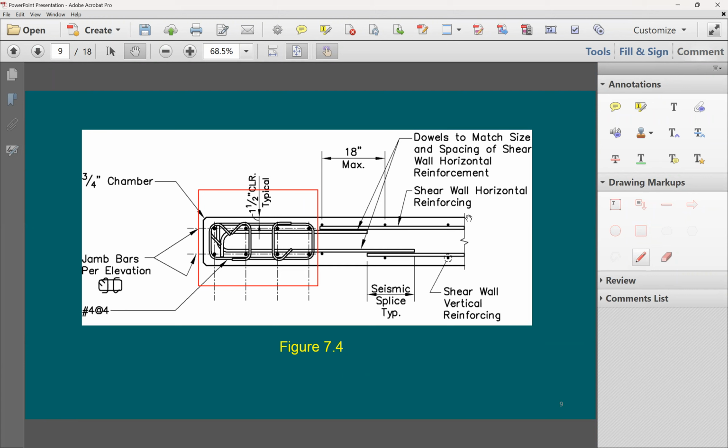And this shear factor here has a range. It's not equal to 2, it's not equal to 3, it's not equal to 4. It is going to have a range here. As it says here, it depends on the aspect ratio of the wall, which means wall height divided by wall length. You see here this ratio, HW divided by LW. Here is the wall length and wall height. When the wall height over wall length is less than or equal to 1.5, you go to 3. This means short walls will have a higher shear factor. So here's the shear factor.